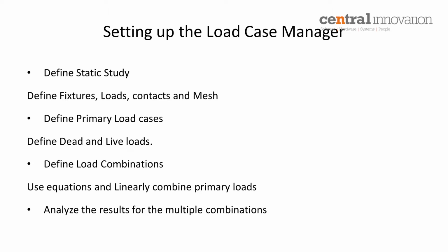The first step is to create the static study. Inside the static study, define all your fixtures, loads, contacts, and mesh. Everything must be defined inside the static study. Once you define the static study, create a load case manager. Start up the load case manager. Define your primary load case by managing your fixture conditions and your loading condition. You can vary your loading condition and create your primary load case.